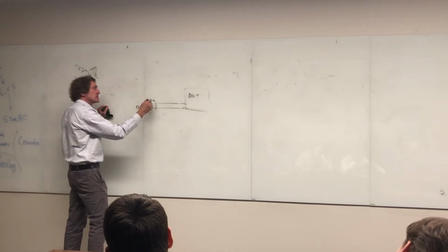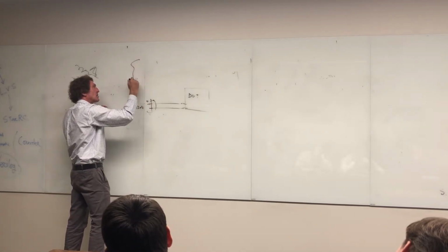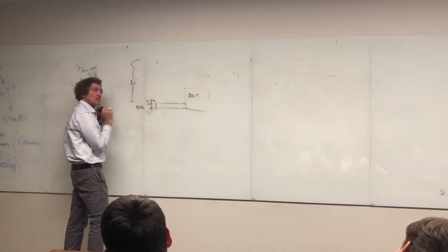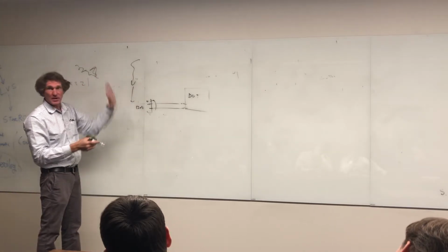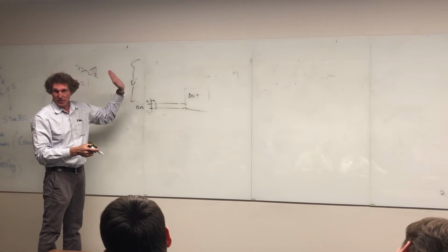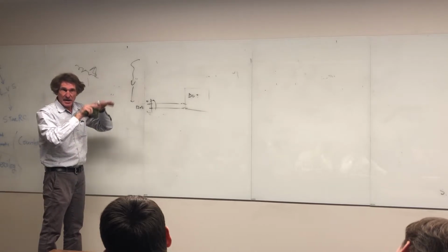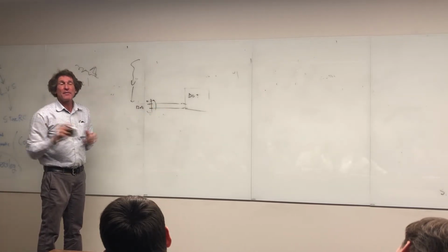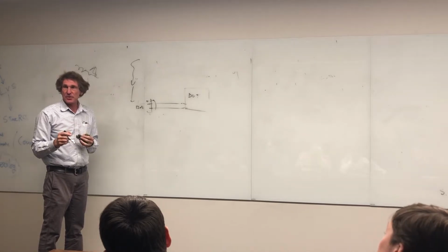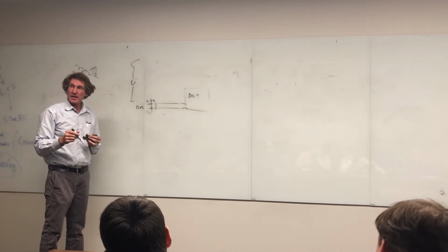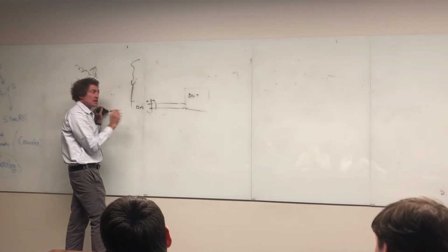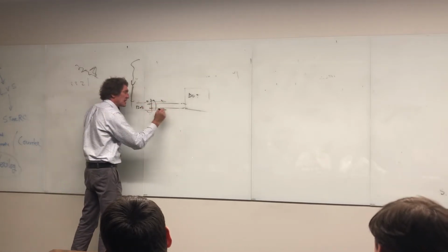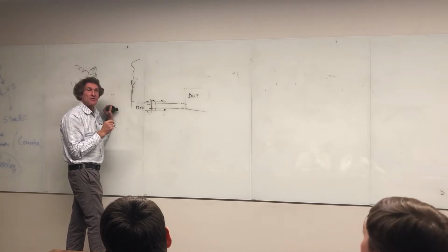Now, if this thing's plugged in there, but somehow out of the blue, lightning hits here, right? Lightning is a single polarity. I mean, it's basically all either positive or all negative current that comes down and hits. And it wants to go in every direction it can to get back to what's called a parent charge. And the way it gets there, usually, when lightning hits, it flows down the path of least resistance, which in this case would be your line right there. Now, it's going to flow down that line.